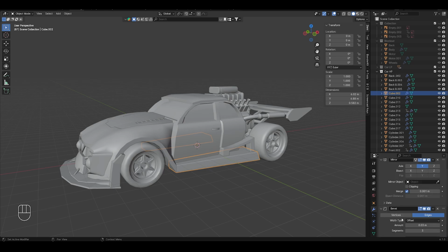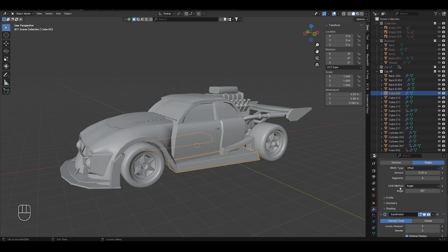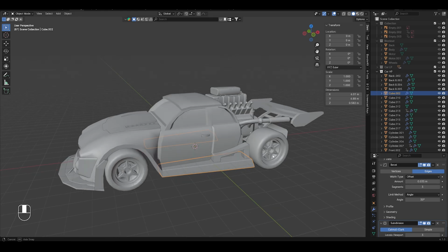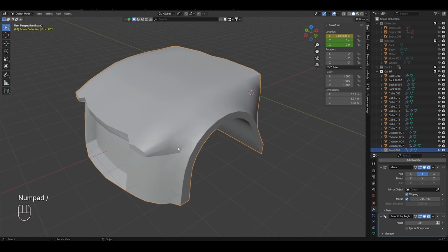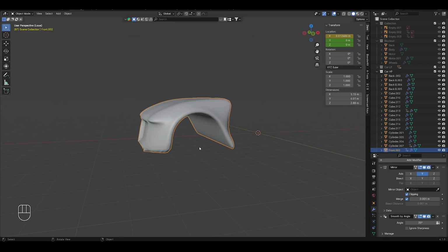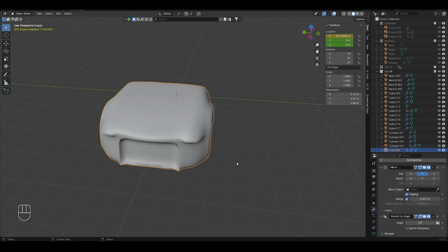With the Blender modifiers, you can change the settings for one modifier and it will be applied automatically. With the Bevel tool, you cannot change the size after the tool was used. Whatever settings you did for your shape, it was already done. But with a Blender modifier, if you don't like the result, you can always go back and change it. But if we go here to the hood of the car and apply Subdivision Surface, we will get a very weird result, and you would ask me why this has happened.